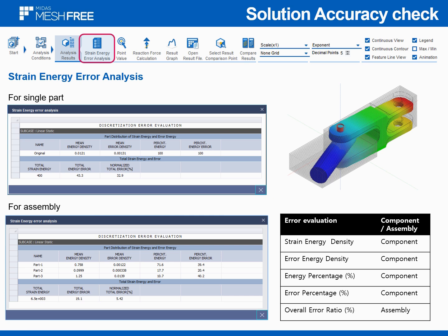There is a table made for a single part and for the assembly, and we have to learn how to get valuable data from this table and to estimate when to stop our solution, when our model is convergent enough to stop and accept the results. So that's the table which will be helpful.